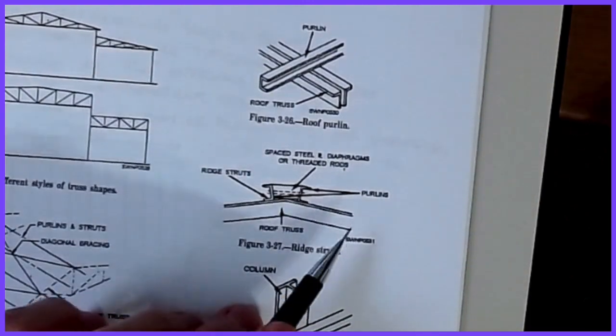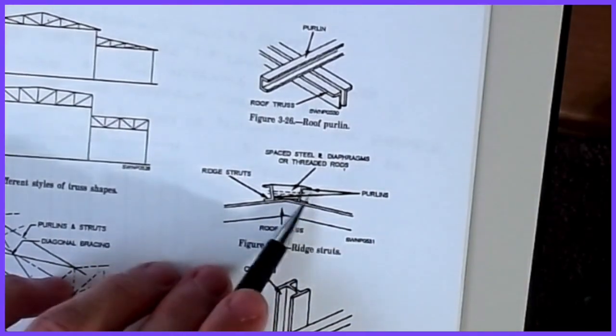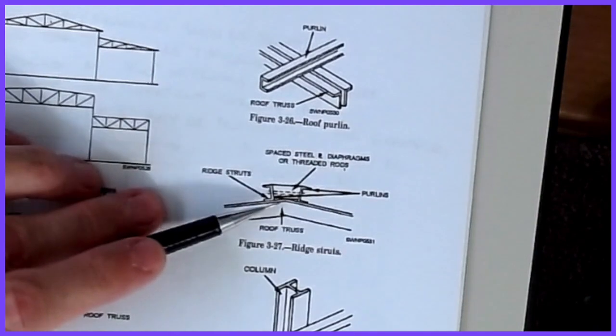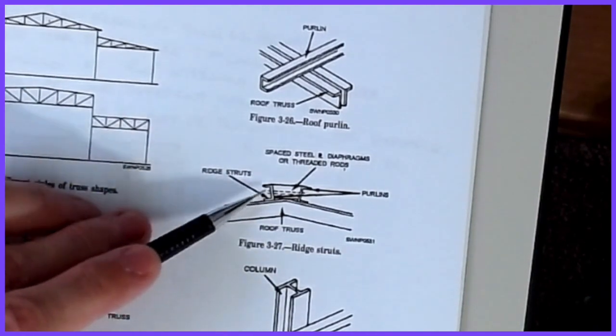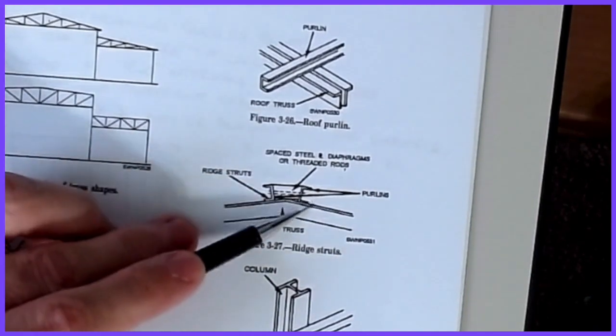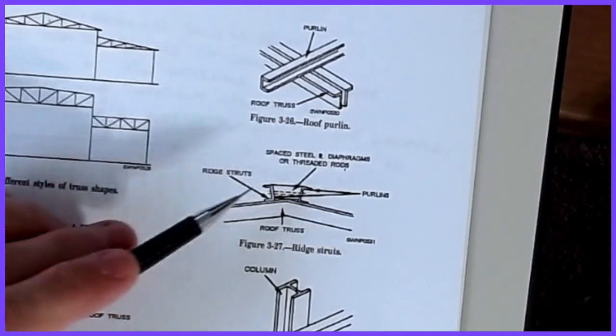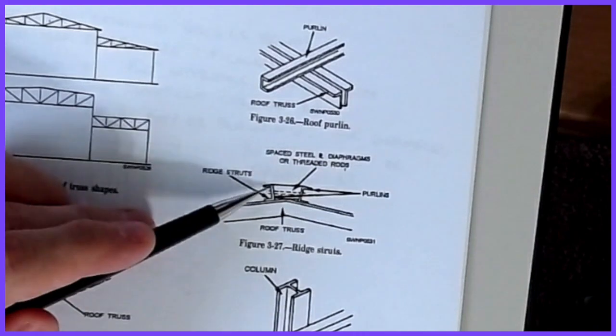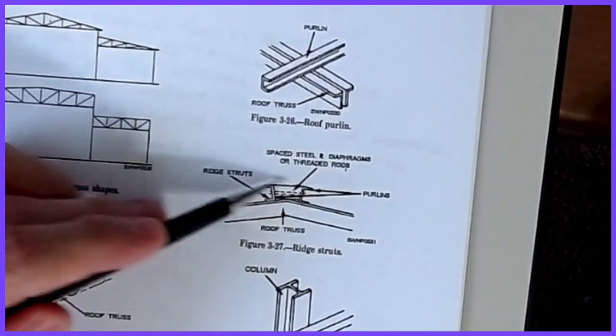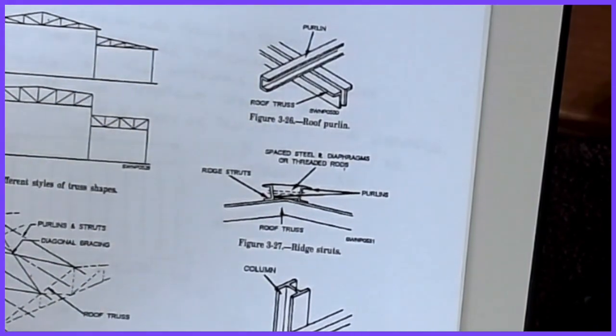And then how do you make the purlins connect? This is kind of an interesting detail: if you have a peaked roof and you lay a channel as a purlin on this side and lay a channel on the other side of the peak, well, now you've got this kind of strange empty cavity that has to happen, and so there has to be an insert piece or something that is used in order to make that connection come over the top of the ridge.